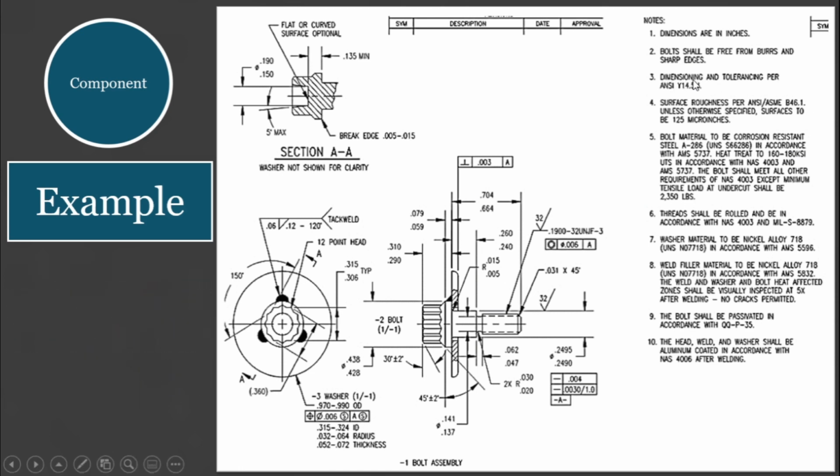Next, it discusses dimensioning and tolerancing. Tolerance means how much the length, angles, or any other specifications of the part are allowed to go beyond or below a given value. That is why, normally, you will see tolerances with a plus or minus sign, just like this indication here. Here, we see 45 degrees plus or minus 2 degrees, meaning the craftsman is allowed from 43 degrees to 47 degrees. It also talked about surface roughness and the material used.